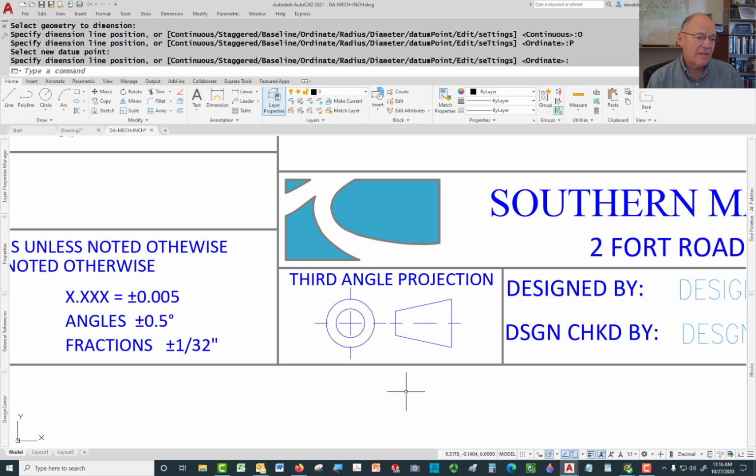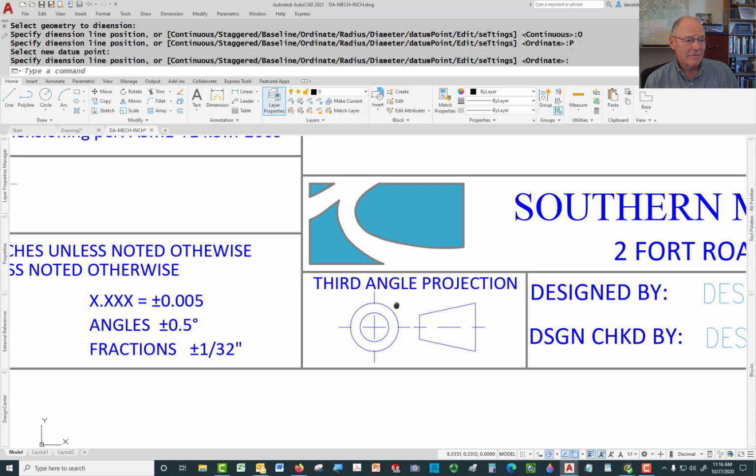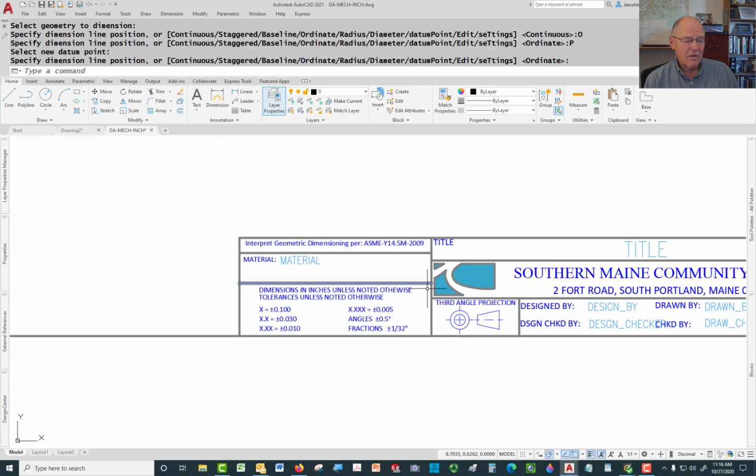The correct symbol for third angle projection is a front view that's two circles representing the end of a truncated cone, and then it has a right side view of the truncated cone. If that symbol, that one right there, was simply moved to the left, it would be first angle projection. I also think it's a good idea to actually identify it with third angle projection in case people misread that symbol. Little icon if you want, some kind of logo, whatever you want there.